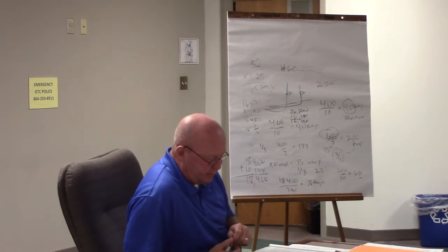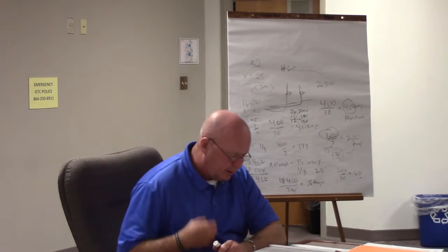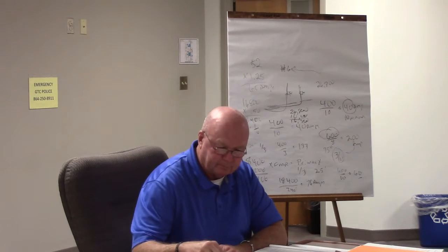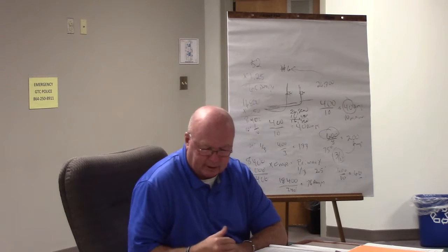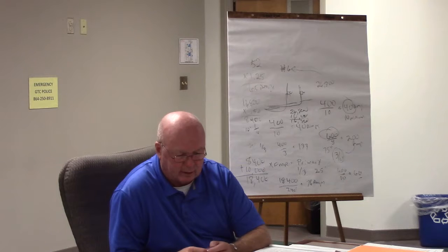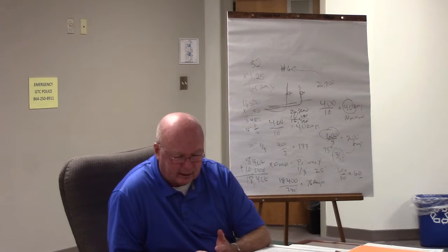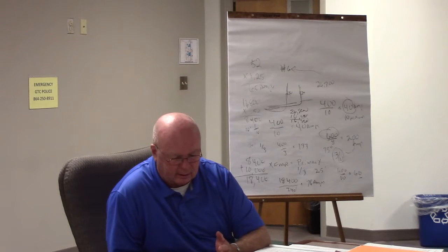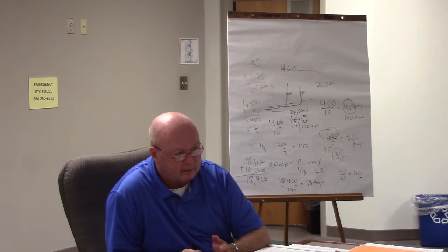220.61 is talking about neutral conductors. Well, there's a couple things as far as, if we're looking at our code book, 220, let's look at 220.61. There's actually a couple of reductions that you can do for neutral conductors. Basic calculation is A. B is permitted reductions. Let's look at that. A service or feeder supplying the following loads shall be permitted an additional demand factor of 70%. Okay, you see that there? Household electric ranges, wall-mounted ovens, counter-mounted cooking units, electric dryers, you can take 70%. So that's the two main things, ranges and dryers.